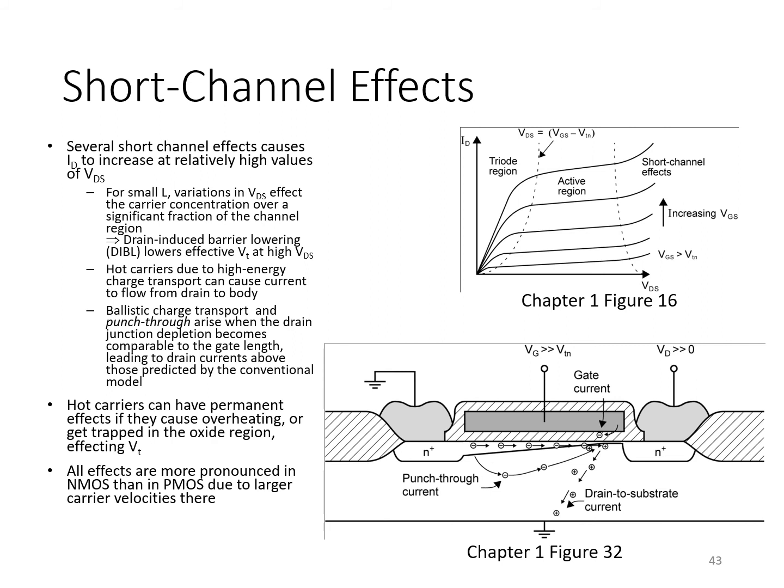So you've got this compounding effect where VDS increases. Not only do you see the typical effect you expect to see in active mode, but at some point the threshold voltage also starts decreasing. And that's where the currents start increasing further.